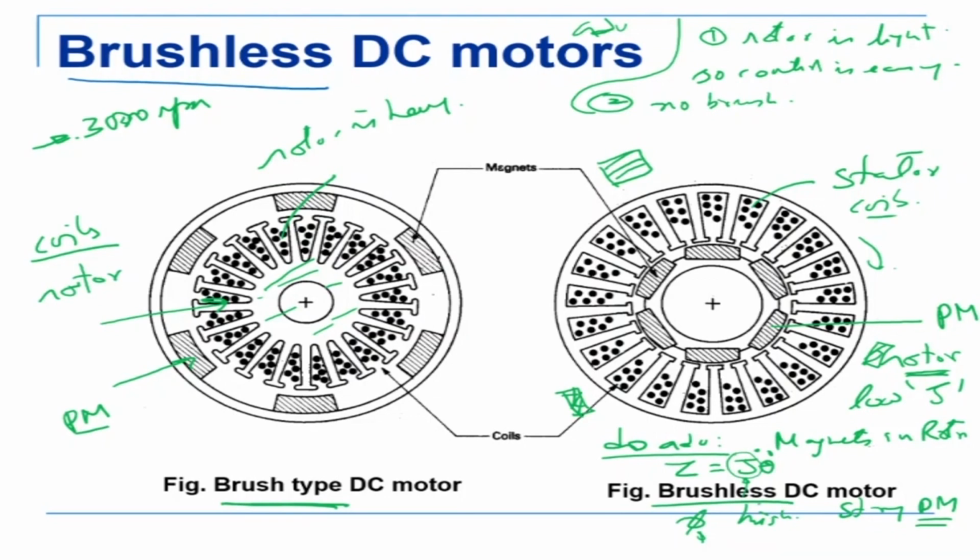So you need very high torque, but very low weight. To get that, these are special magnets, which are made using powder metallurgy, and that is what adds to the cost. So the disadvantage is magnets in the rotor are very expensive.